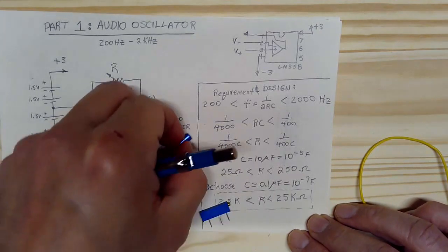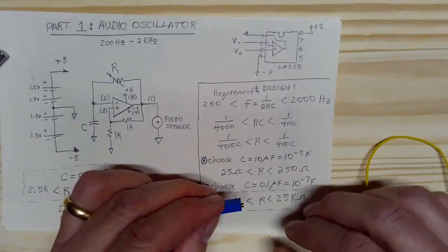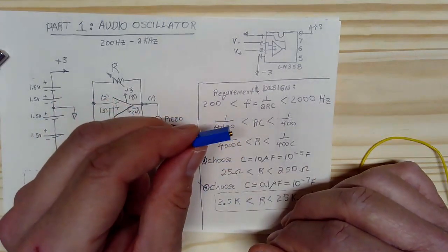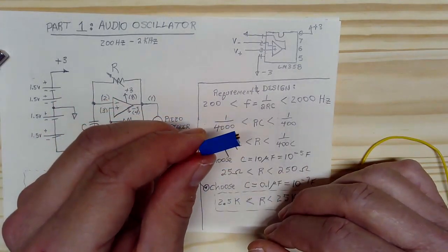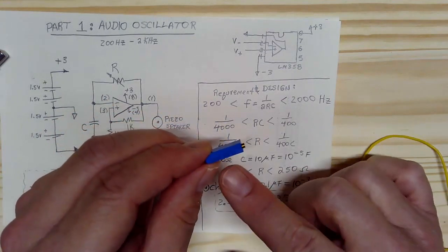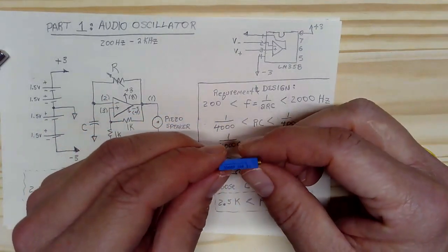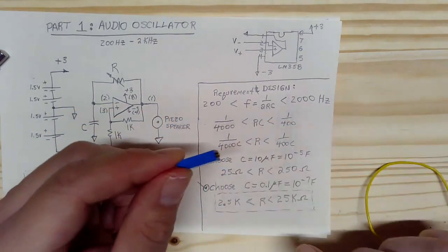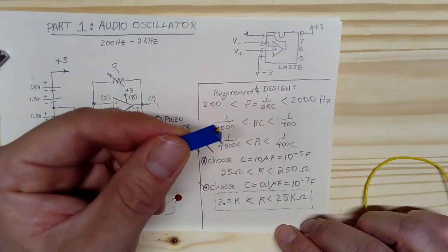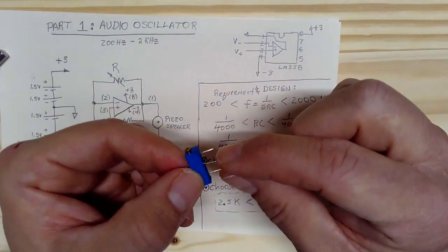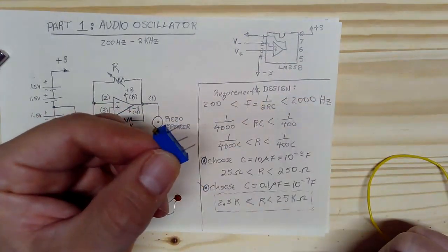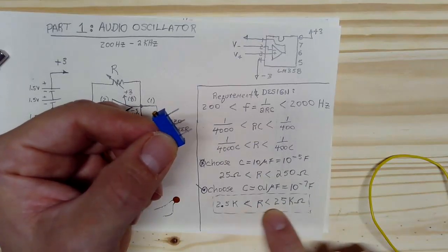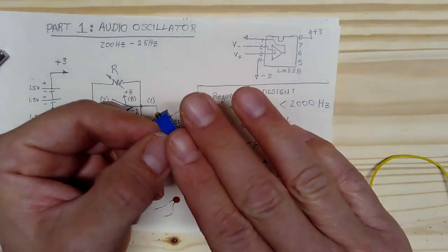And so now, fortunately, in the kits, you have 2 of these. You have a total of 3 variable resistors. And in the previous part of this lab, in 4.1, we looked at the 1 megohm variable resistor that was labeled 105. You also have 2 100 kiloohm variable resistors that are labeled 104. And so what we're going to do is we're going to use this. This is a variable resistor, and you can adjust the resistance between these 2 terminals anywhere between 0 and 100K. And so you can see that this range of resistance values is nicely going to be covered by the lower end of this.